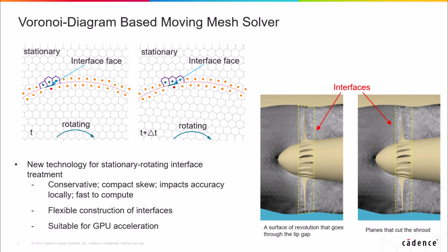Fidelity LES utilizes a Voronoi diagram-based technology for stationary rotation interface treatment. It is conservative, compactful, impacts accuracy locally, and is suitable for GPU acceleration. This allows for flexible construction of interfaces.